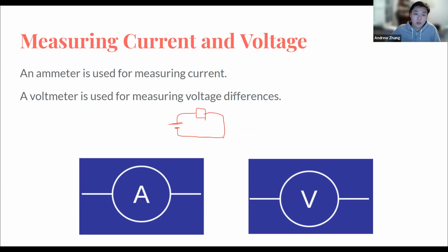And now we want to know what would be a place that we could put this voltmeter to find something that's actually useful. How can we use a voltmeter that's actually going to give us a normal reading that's not just something like 0? We could put something here, for instance, to measure between this point and this point, because then we would have a positive resistance in between, and that would tell us the voltage difference. So we could slap it right there. That's our voltmeter.